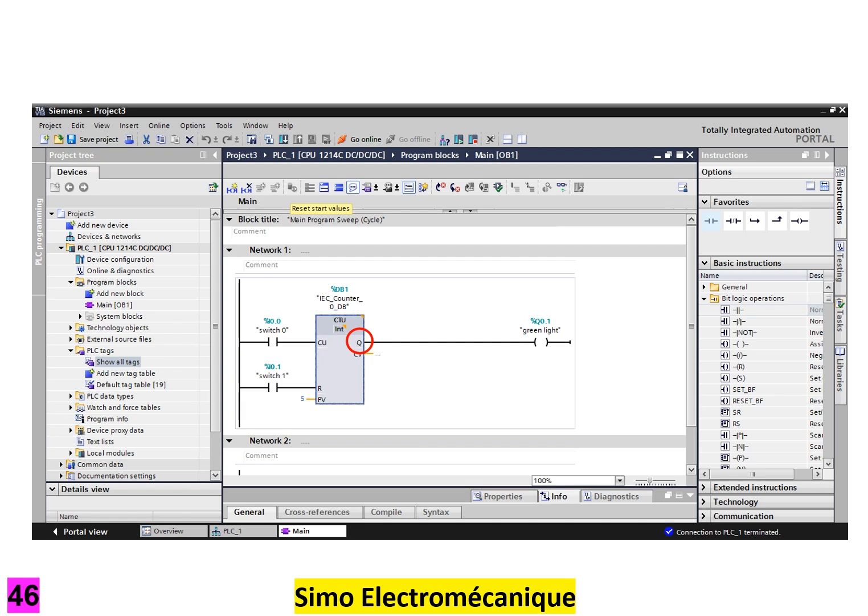CTU stands for count up. In operation, CTU counts the number of times input CU is switched on. Once the counter reaches the value in PV, program value, output Q is switched on. To reset the counter back to 0, input R must be activated. Output CV can be used to read the current count value to trigger other events at certain values.